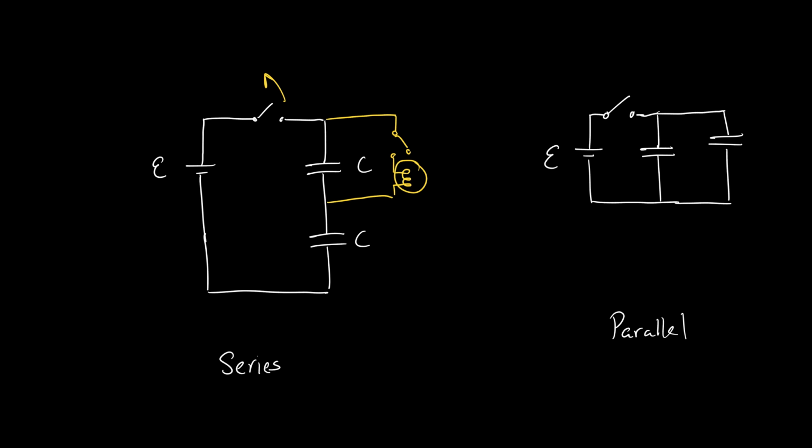In an ideal world, a capacitor will remain fully charged for the rest of its usage until you discharge it. In fact, one of the things we'll do in labs is make sure that we discharge our capacitors before you store your circuits, because they can remain charged for a long time.